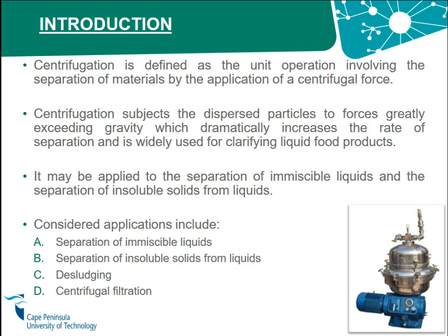We are mostly focusing on the centrifugal forces that are applied. So, what are the considered applications? We consider four applications, especially for this presentation. We look at separation of immiscible liquids, we look at separation of insoluble solids, removing solids from liquids, and we look at dislodging and the centrifugal filtration.